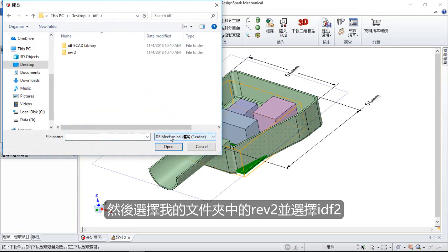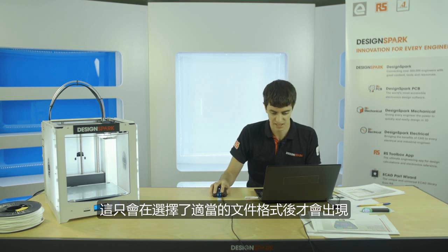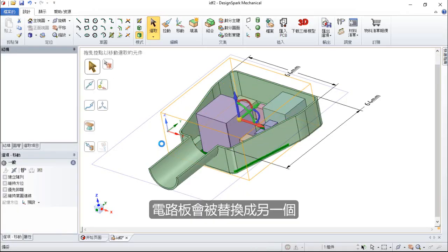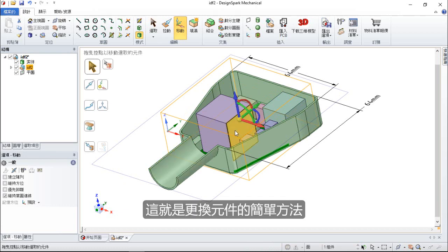I'm then going to go to revision 2 in my folder and select IDF2. This will only appear if the appropriate file format, such as ECAD file, is selected. So when I click open, my circuit board is replaced with a different one, and that's how simple it is to replace components.